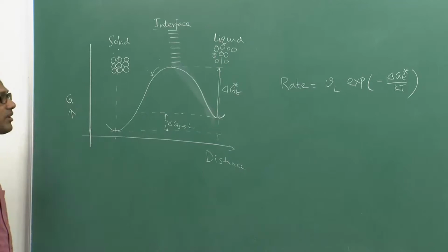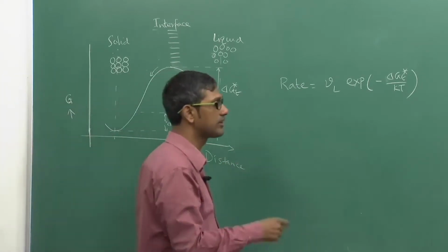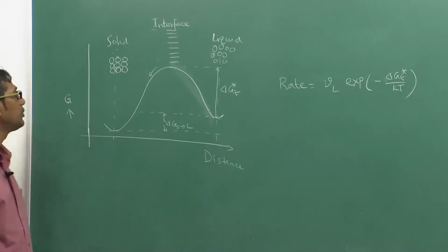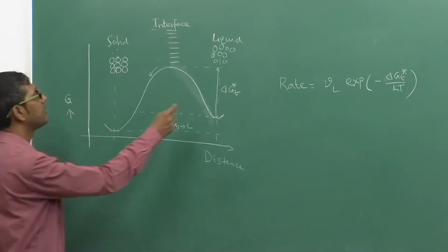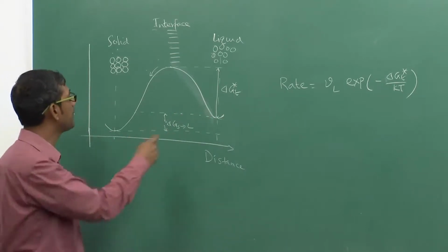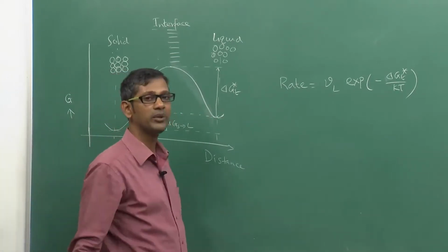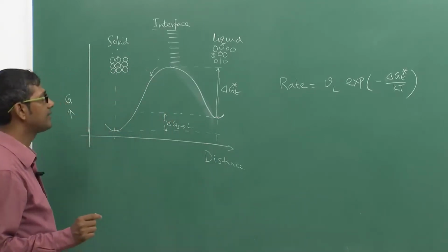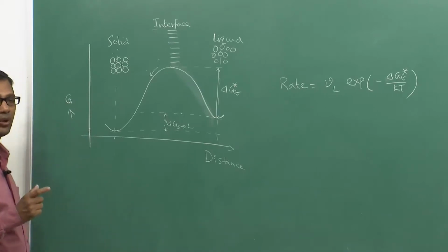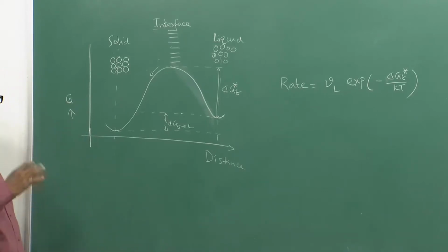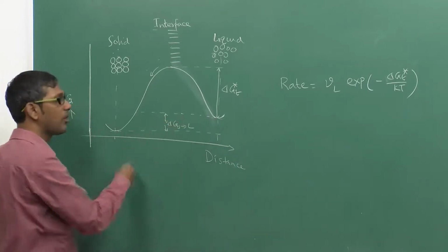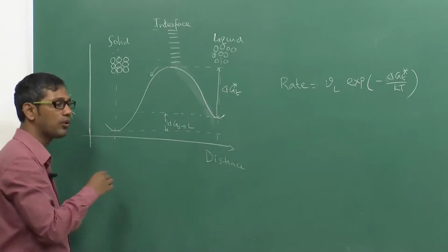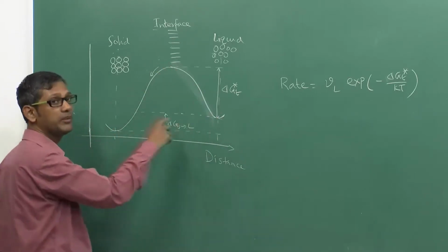Okay. So that's how things can actually happen. Now, using this concept, for two different types of interfaces, let me explain. I can then do a flux calculation from the liquid to the solid, and explain how the flux can be calculated. Obviously, as I told you, when you are talking about net growth, meaning net atoms getting attached from the liquid to the solid, we need to consider both the jumps from the liquid to the solid, which is known as a forward jump, and also the backward jump from the solid to the liquid.